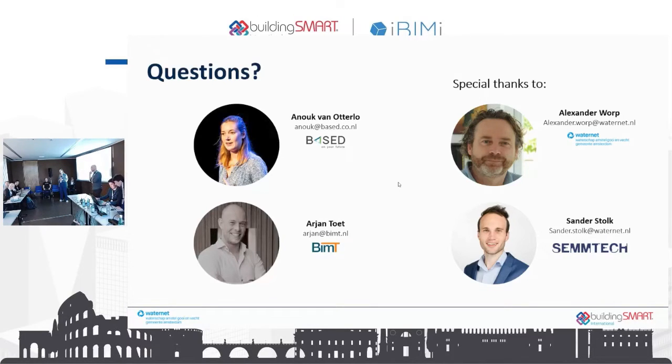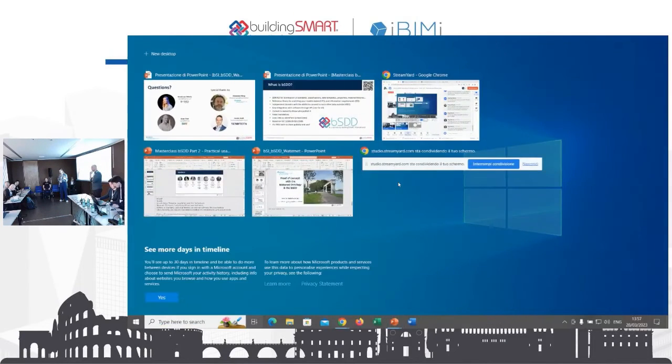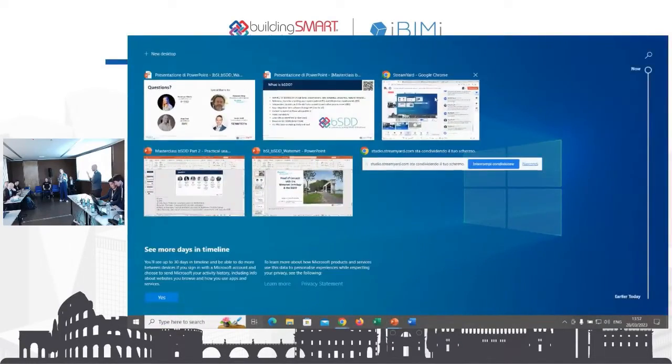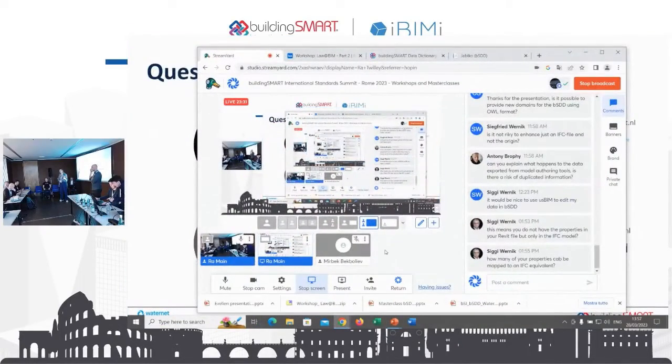You have the model in IFC. You put the property, you fill in the property, you use it, and later maybe you need to update the 3D model, and then you re-export an IFC. When you bring back this IFC, do you keep all the properties that you put on the previous one on top of the new IFC? No, you lose everything. Yeah, now you lose it. You have to reuse the IFC. You make an export, and that IFC you have to reuse.